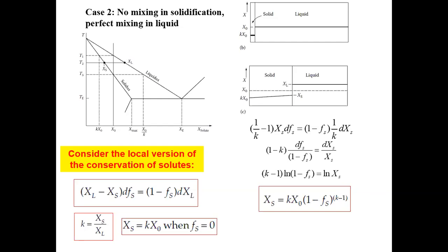Okay, so this is about the mass, right? And if you have this solid composition, you can always very easily get the liquid composition. Although it's less interesting. So the liquid composition is going to be uniform. So this is not going to be a profile. It's only going to be a number, right? So it basically tells you what the number is throughout the liquid. Okay, it's a function of the amount of the liquid with this relation. And if you compare these two, the only difference is that we take the factor k away, because the ratio between these two is going to give you a factor of k, right? And then we simply write 1 minus fs as fl because it's more intrinsic to the liquid. Okay, so that's what we have for this.